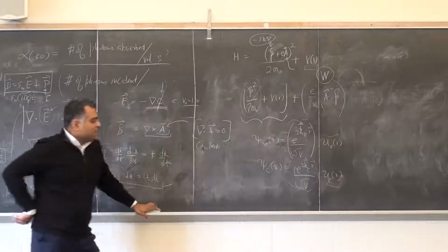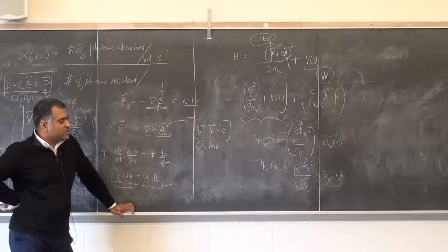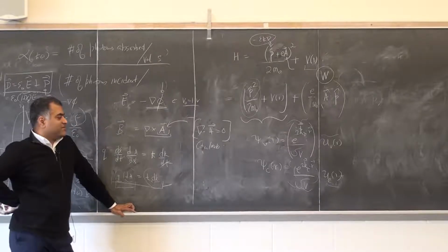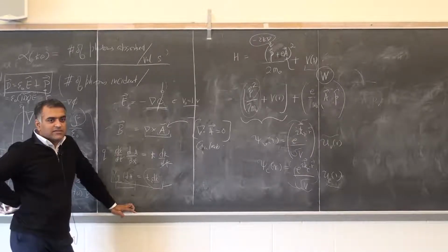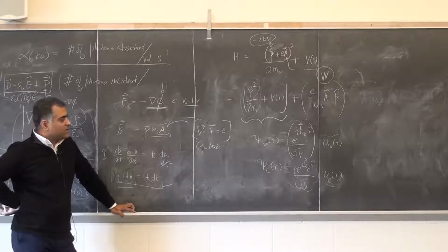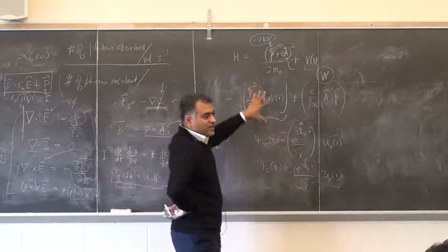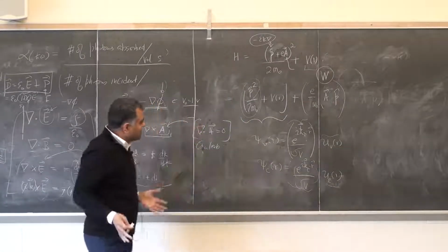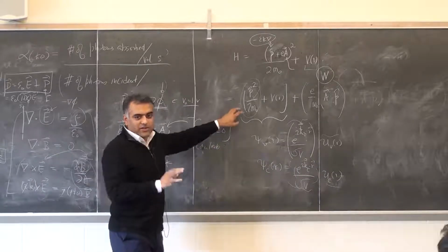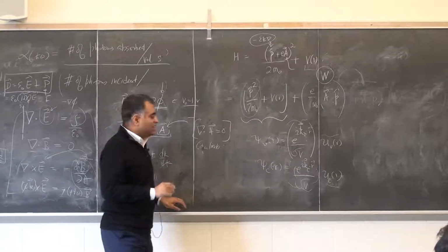And what I'm trying to say is, for most cases, if my semiconductor laser is putting out about 50 milliwatts, it's still valid. At 50 milliwatts, that term is way smaller than this one. But if you blast it with a much higher intensity, then it can become comparable. So we're not looking at those nonlinear terms.